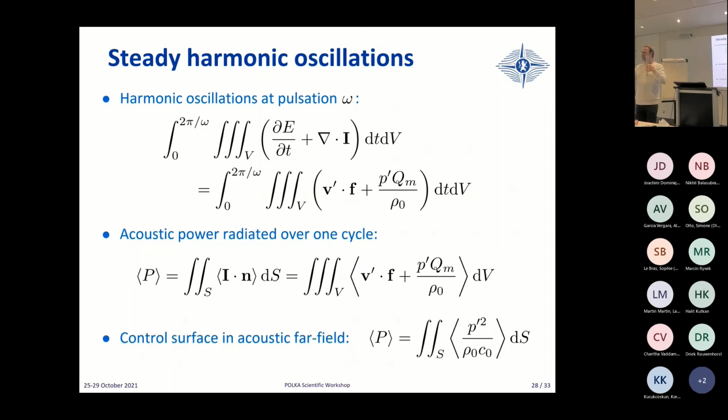That's obvious. So it means that there must be an acoustic resonator somewhere, and the resonator is a pipe, an open pipe. You know this as an organ pipe, maybe. So the organ pipe, you have boundary conditions, pressure fluctuation 0 here, pressure fluctuation 0 here, because basically you are at the atmosphere. So you know that the modes are going to look like half wavelength sine waves and multiples of half wavelength. So the first mode is looking like this for the pressure, the next one will look like this, and so on and so forth. As long as you respect P prime equals 0 at the boundaries, it's a mode of your pipe. We are going to look at the first mode. So you have a resonator, you have a pure tone.